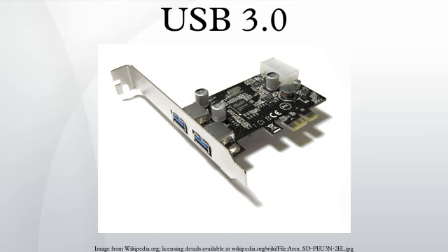A USB 3.0 standard B receptacle accepts either a USB 3.0 standard B plug or a USB 2.0 standard B plug. Backwards compatibility applies to connecting a USB 2.0 standard B plug into a USB 3.0 standard B receptacle. Though, it is not possible to plug a USB 3.0 standard B plug into a USB 2.0 standard B receptacle, due to a physically larger connector. The standard B is used at the device side.